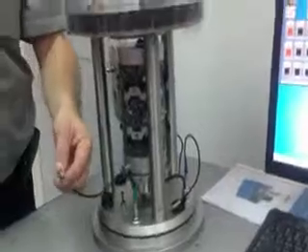Our transducers, the 0 point is always in the middle of the transducer. So this is calibrated plus minus 0.5 mil. So when the transducer's here, it is plus 0.5 mil. If I press them fully, this is minus 0.5. Yep. So the 0 point is in the centre. So for this we can adjust this a little bit more.